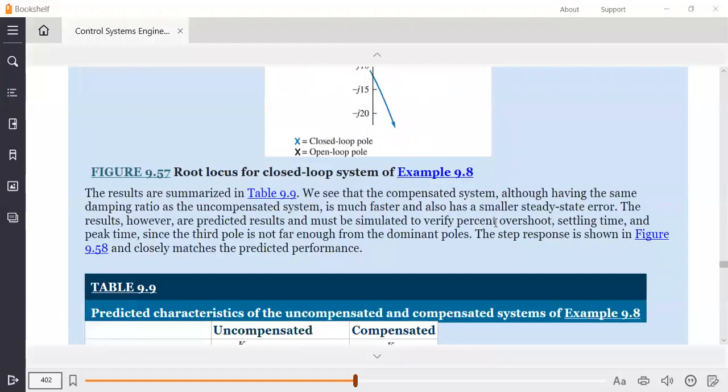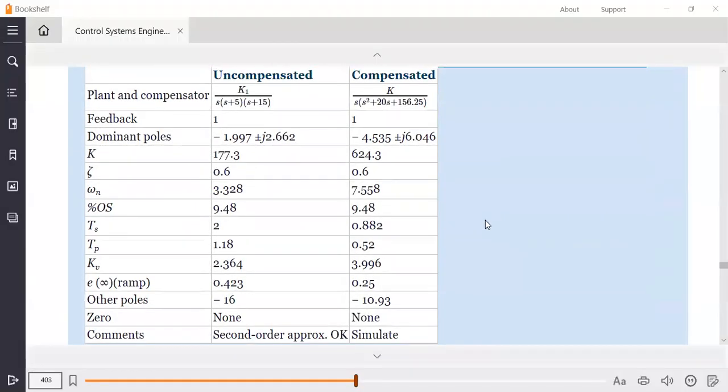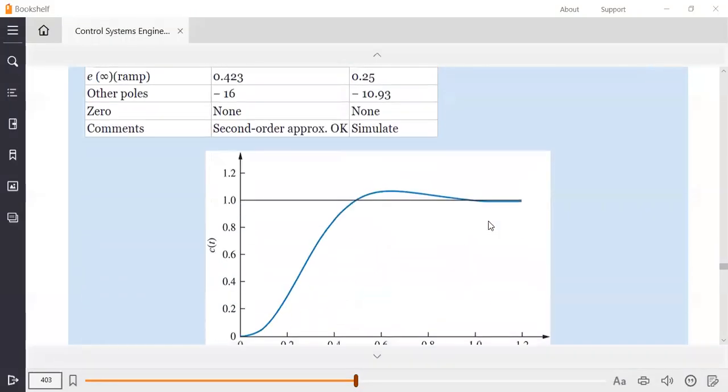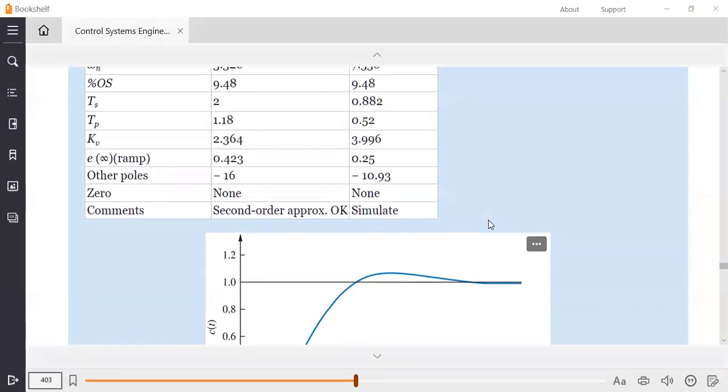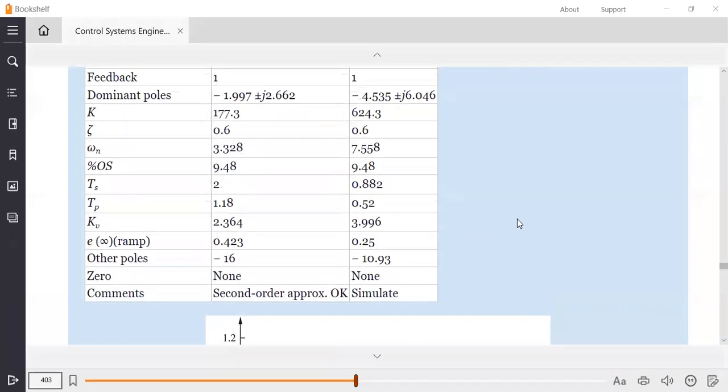And you actually have to figure out the table again. If you look at the table, as you can see here as well, the dominant pole, the second order pole, and the third order pole are not five times away. So you actually have to verify by simulation again.